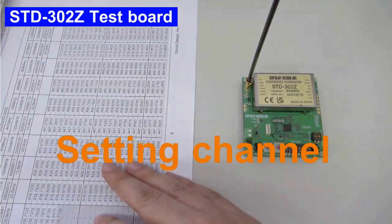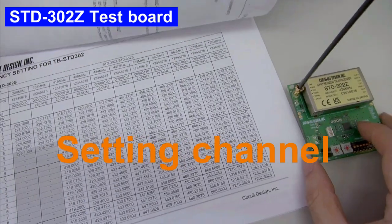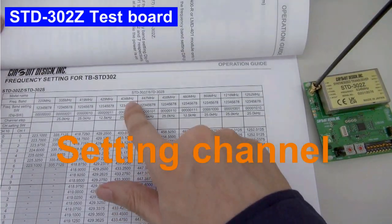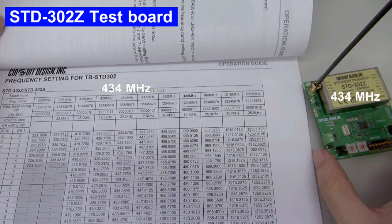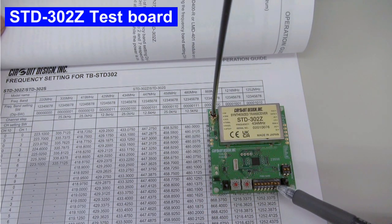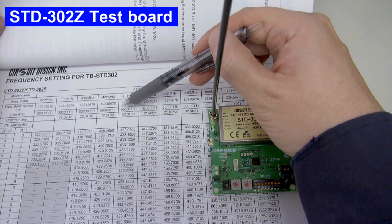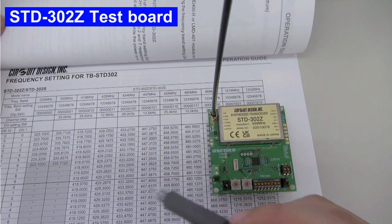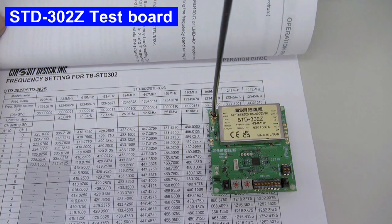So let's look at setting a channel. Refer to the operation guide for the test board. First, we confirm the module for the band we want to use. The dip switch here sets the band. The channels given here can be selected using the rotary switch.